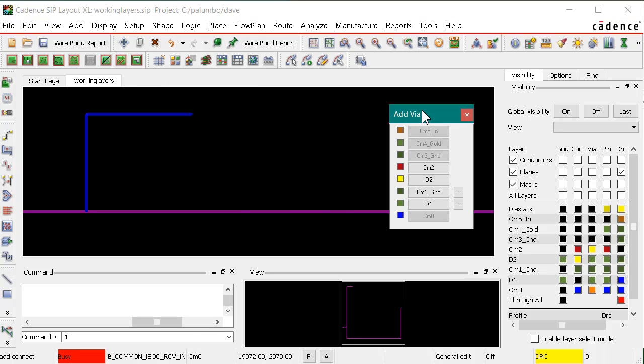And we're going to be using what we call a working layer model. In class, we had talked about the alternate and active layer model, where we were just adding a via and it was swapping our alternate and active layer. And that was very convenient when we were trying to add stacked vias. But for your staggered vias, the working layer model is going to be more convenient. And after we do all the setup, we'll also go through showing you how to use the working layer model.